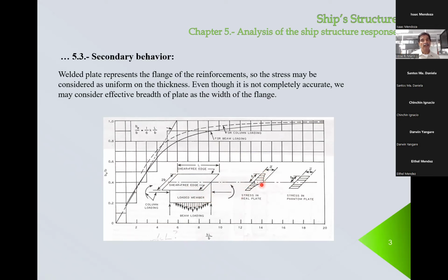Okay, so in order to estimate the maximum normal stress, what we do is we define an equivalent normal stress distribution with uniform maximum value for the normal stress. But since this increases, you see that here I have a lower value than the maximum.